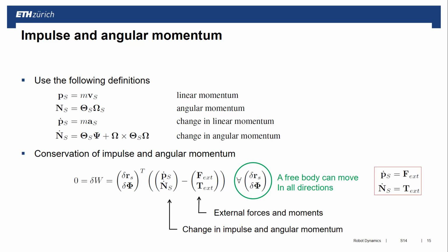So that's the most simple setup. Now, what we did in the second step is, instead of going through this standard Newton-Euler for individual free floating bodies with the free cut, we said, why don't we change this part here? Why don't we make sure that we are formulating this equation only in directions which are feasible given the constraints we're having?